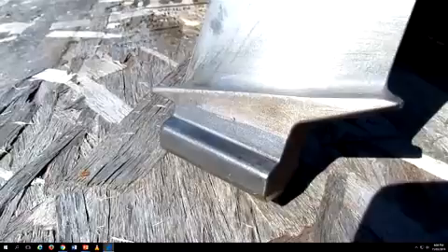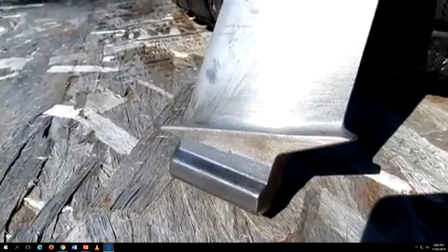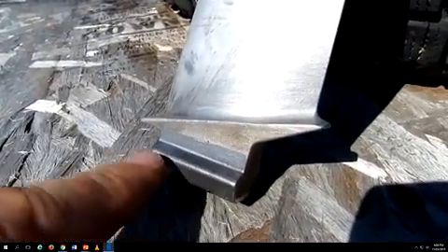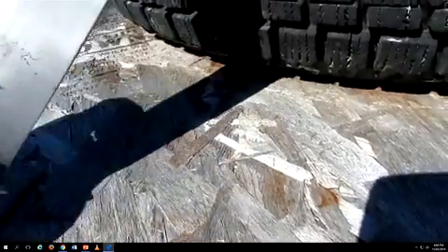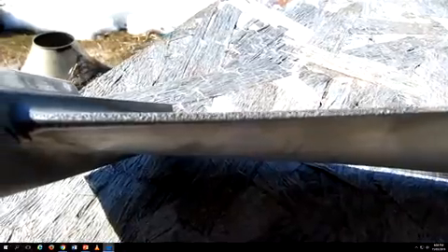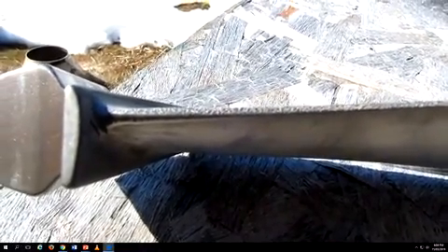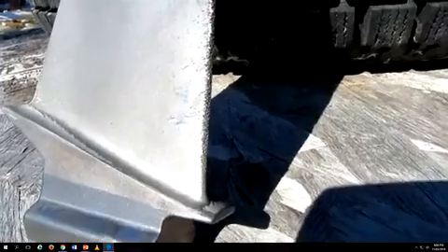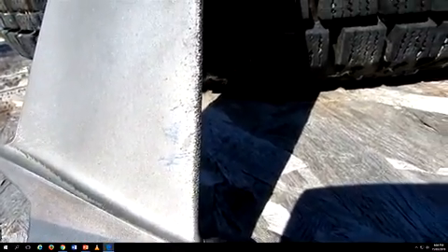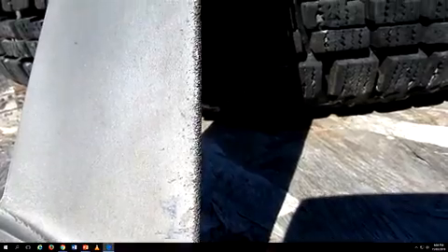There's another very good example of what happens. This can't be repaired. Or it can be repaired up to a limit. This is the leading edge of the compressor rotor blade. You see that rough texture with all the little pits and holes and moon-like surface? You see that leading edge? All the pock marks are from tiny particles of solid debris, sand or dust, smashing into that at very high speed.